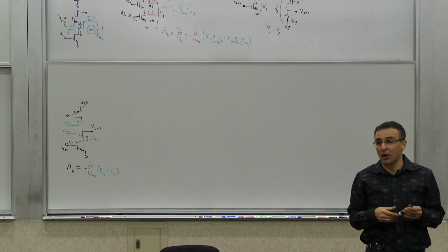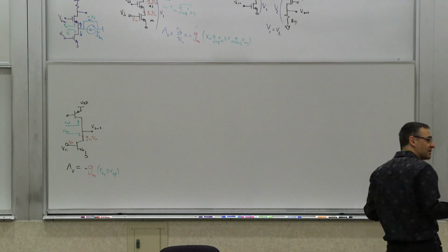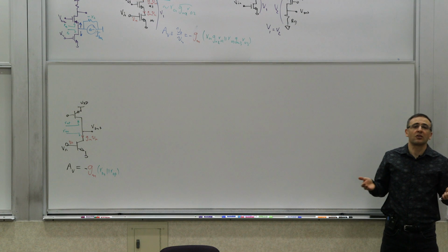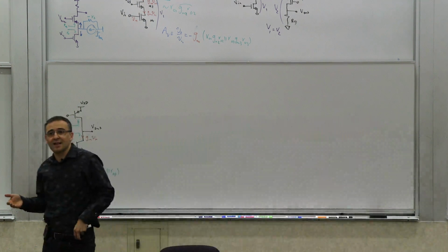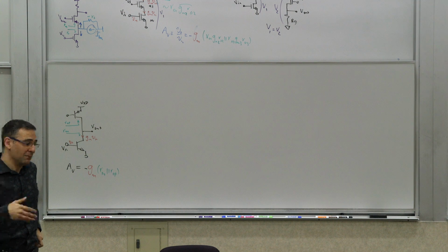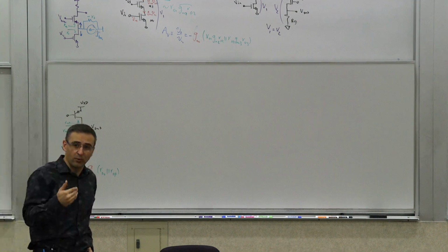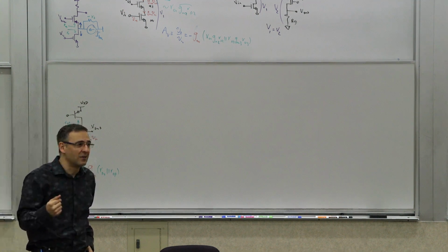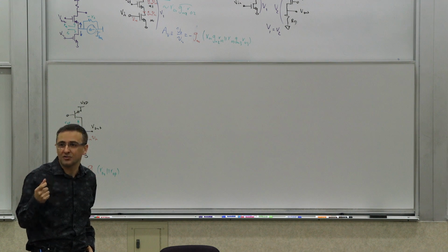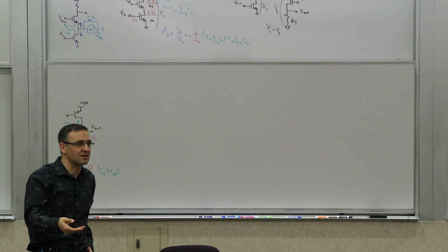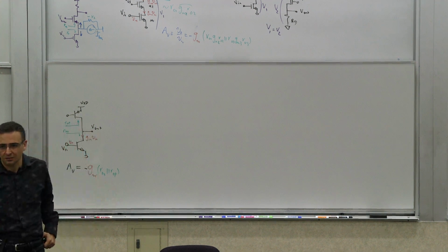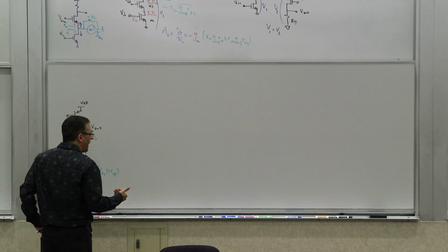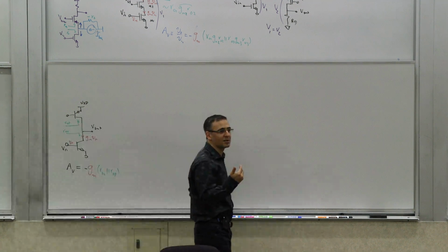Now, some of the bipolars in there are actually HBTs. They're silicon germanium, for example. A very common form of this are silicon germanium BiCMOS processes, where you get an incredibly high frequency bipolar NPN, whose base is essentially made out of silicon germanium alloy. And we talked about how it enhances the performance of the system by improving the emitter injection efficiency and the base resistance and all those things when we were talking about the device. And you also have a complementary CMOS process.